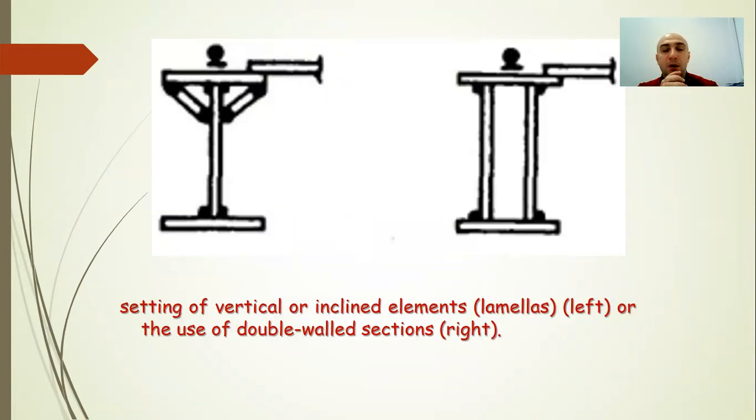The higher intensity of operation of special mode cranes often leads to damage in the support zone of the wall of the crane girder. In such beams, in order to reduce the level of local stress in the wall arising from eccentric application of the crane load, it is advisable to increase the torsional rigidity of the upper chord by placing vertical or inclined elements, or to use two-stage sections.